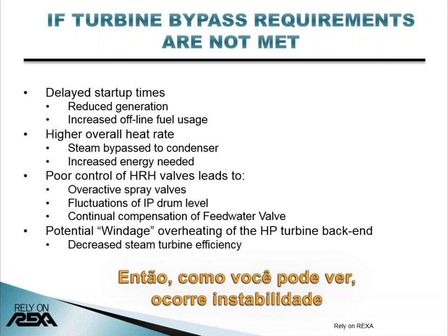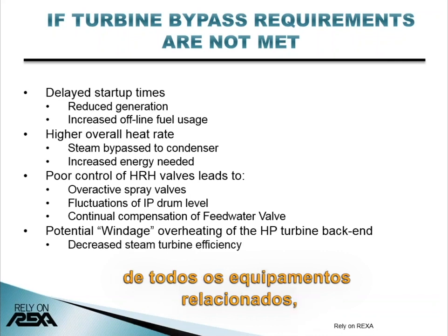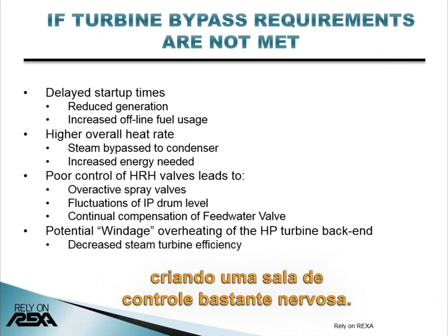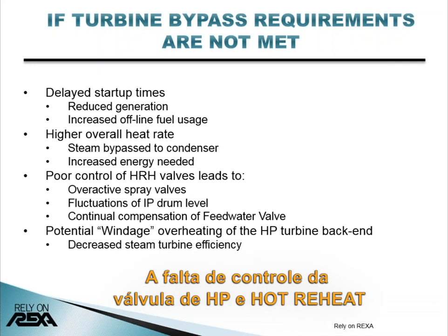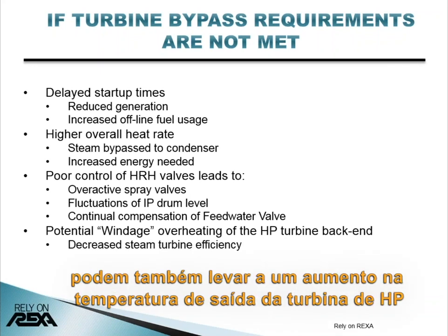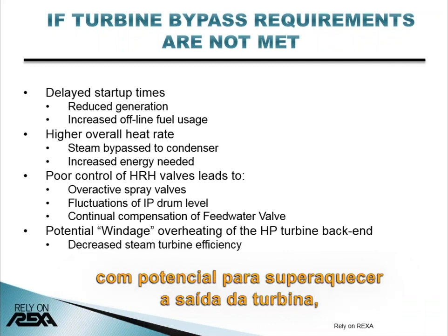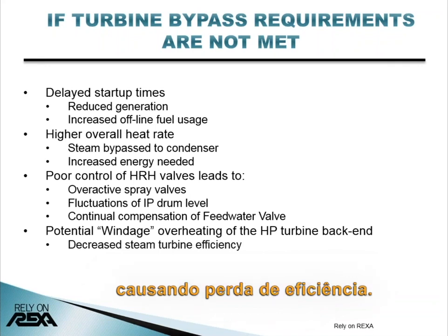So as you see, instability of all related equipment occurs, creating a very nervous control room. Lack of control of the HP and hot reheat valves can also lead to increased HP turbine exhaust temperature and potential windage overheating of the HP turbine back end, causing efficiency loss.